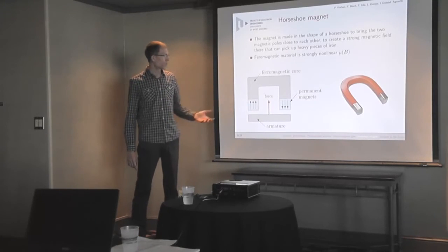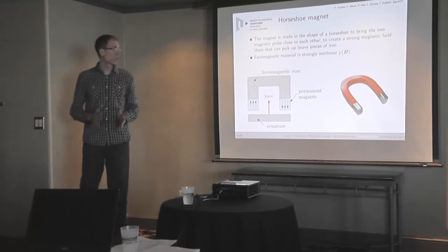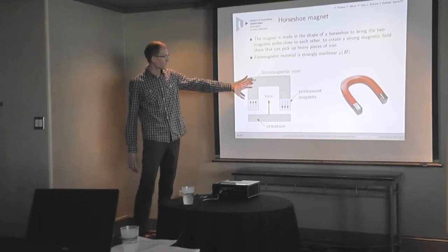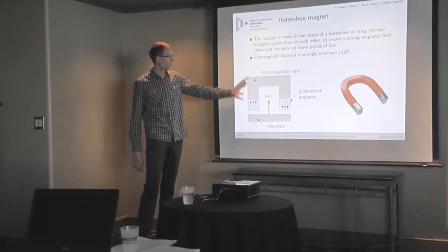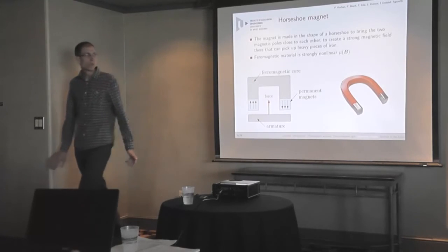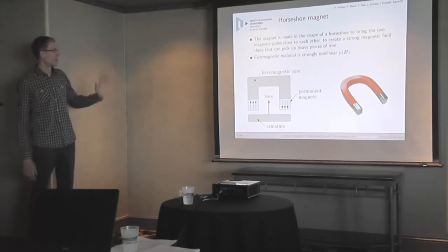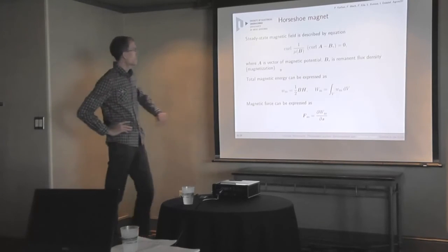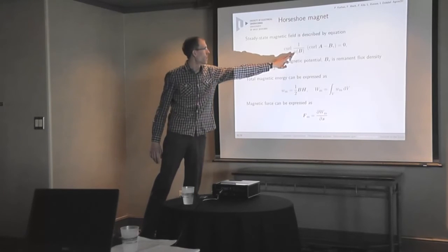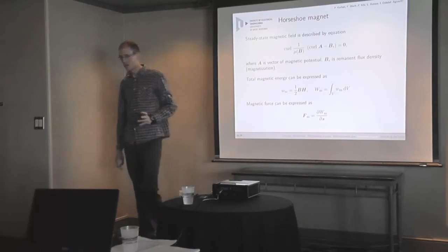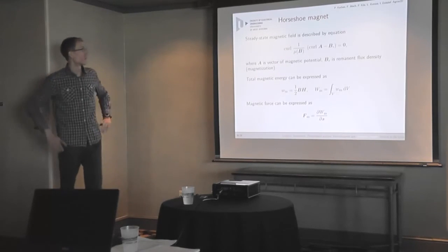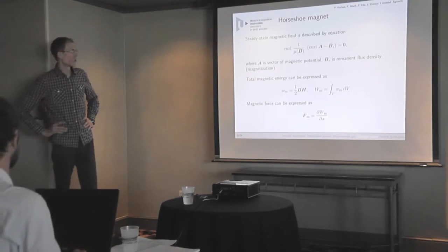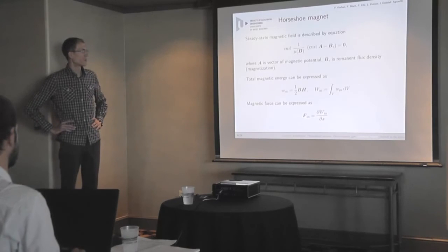We will use the calculation from the total energy of the field, which is obtained as an integral. Then the force is defined. Mechanics is a derivation of the energy. The new thing here is that we are using a nonlinear parameter for permeability, which has a very strong nonlinearity. So we will use Newton's solver.